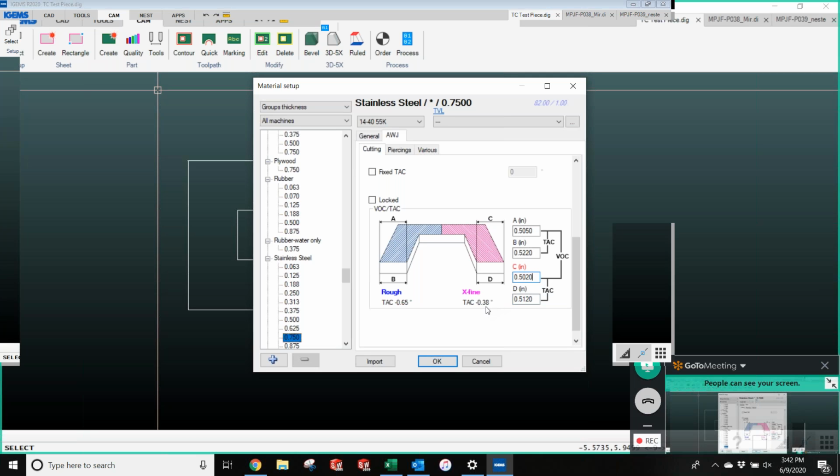And then you'll see as I click out of these boxes here that these numbers change. So then it basically interpolates those from the Q5 to the Q2 speeds there. So you can use these boxes here to fine tune your taper values.